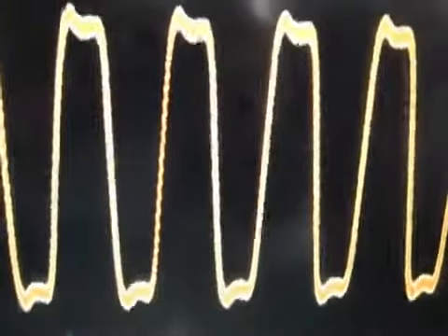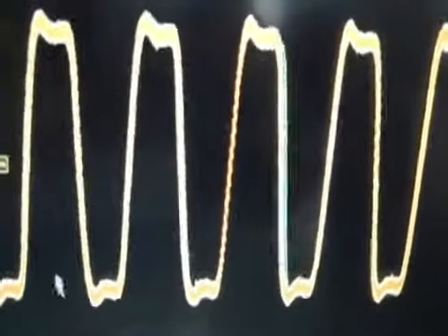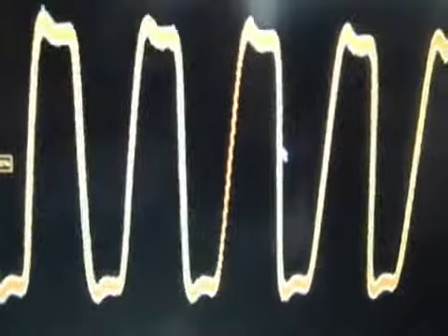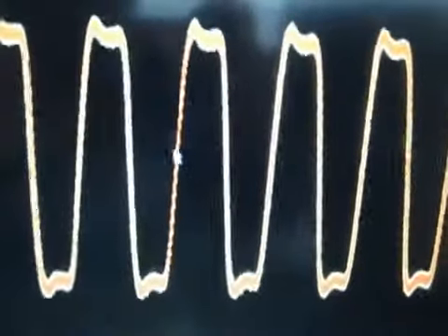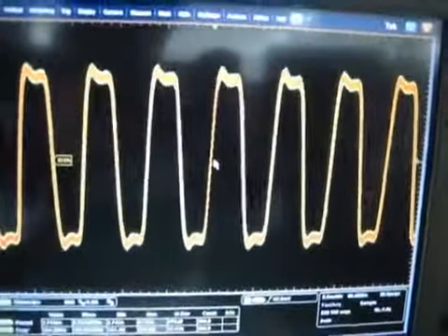there's some intermittent timing distortion on the signal. Let's zoom in and move close to this area. We will see, okay, on the falling edge of the clock, it looks like there's some jitter issue. So we trigger here, and we try to isolate this problem.